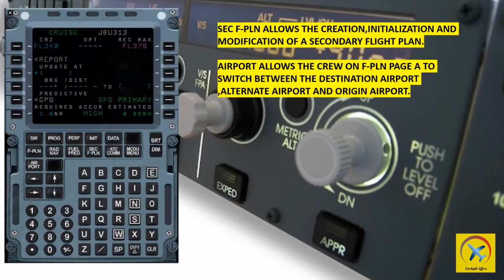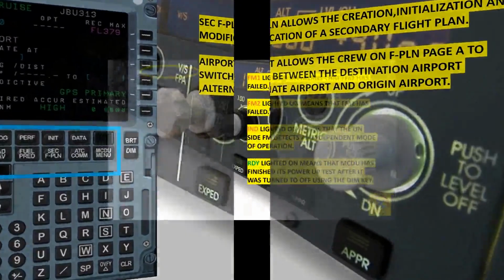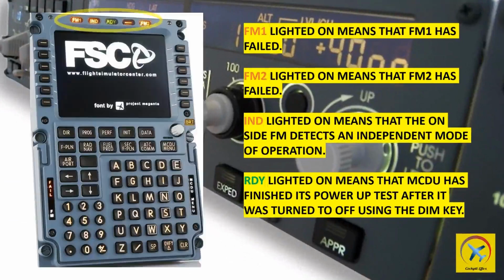Performance pages allow the crew to optimize the speed or Mach targets for each phase of flight. Progress page enables the crew to monitor the progress of the flight, to cross-check or update the flight management position, and to alter the crew's flight of the aircraft. Radio navigation displays the radio nav aids currently auto-tuned by the system. It also allows the pilot to select other nav aids.